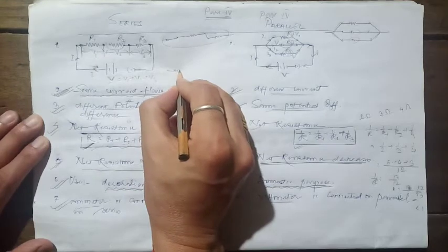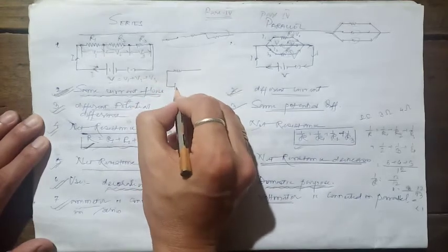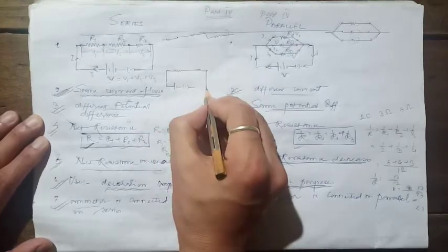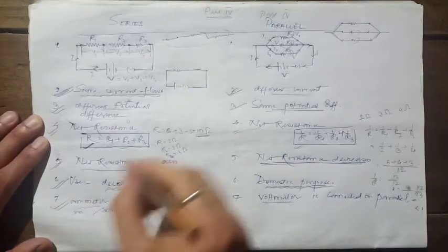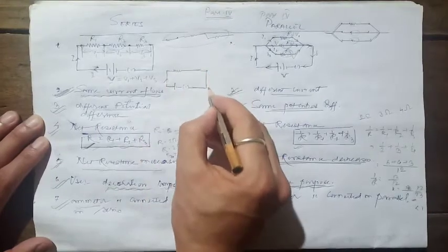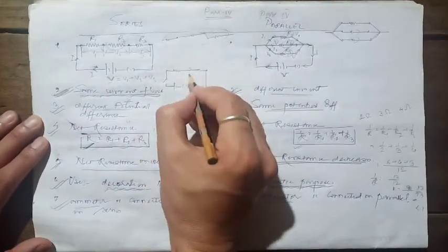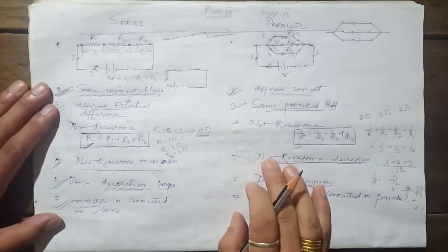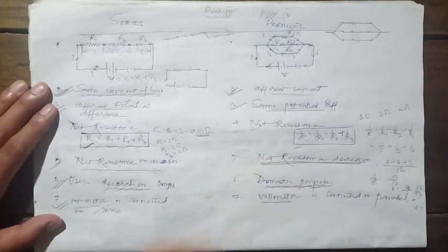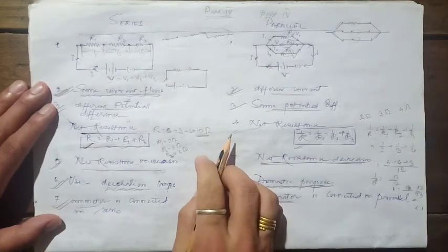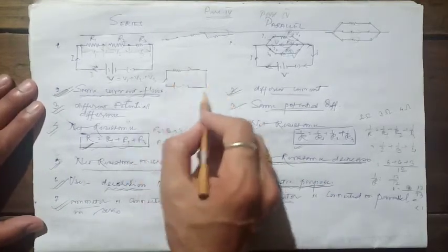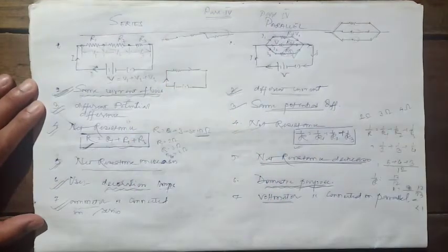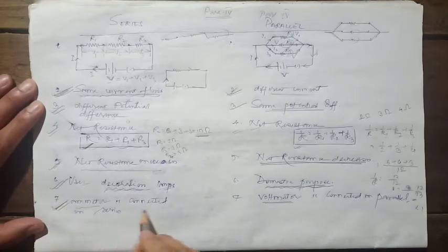Students, suppose I have a circuit here. Let's say this is the circuit. The current flows through this circuit. There is a certain amount of current flowing through these resistors. I want to know how much current is flowing through these resistors. To know that, I have to connect an ammeter, because the ammeter will tell us how much current is flowing in this circuit. Now to connect this ammeter, as I mentioned here, the ammeter should be connected in series.